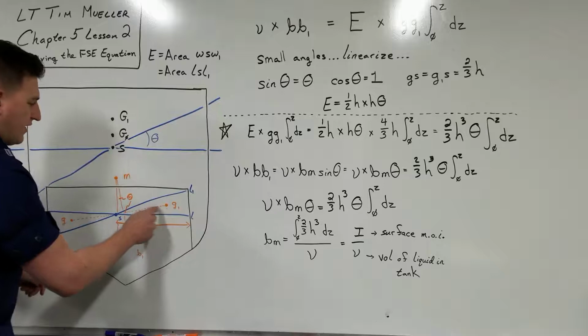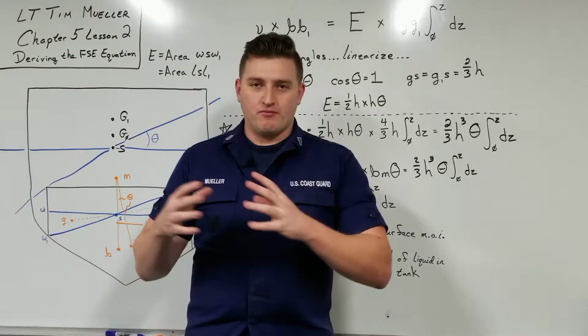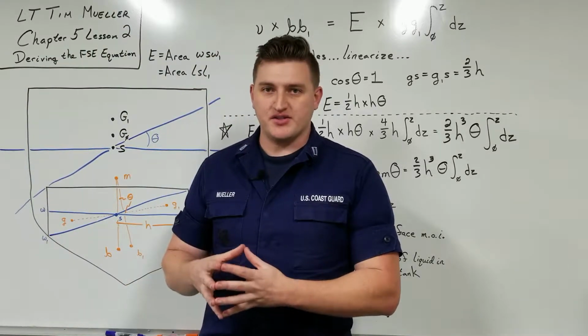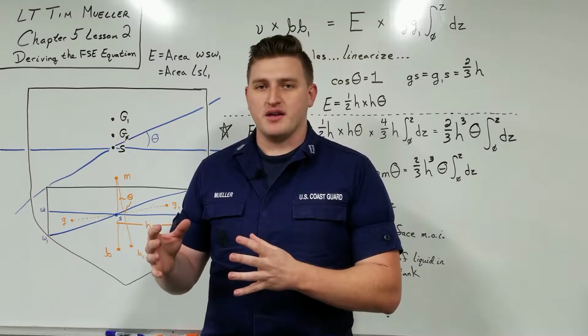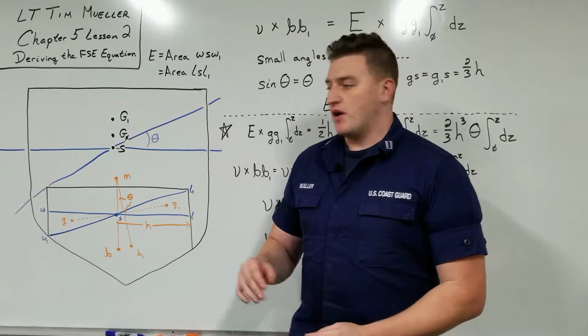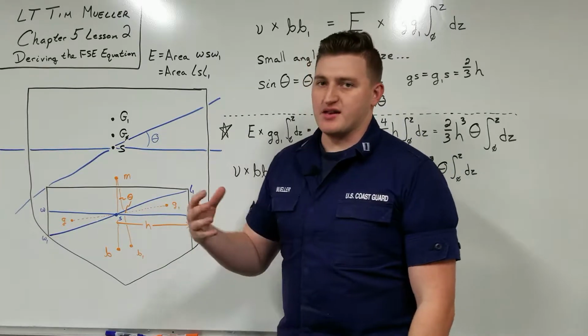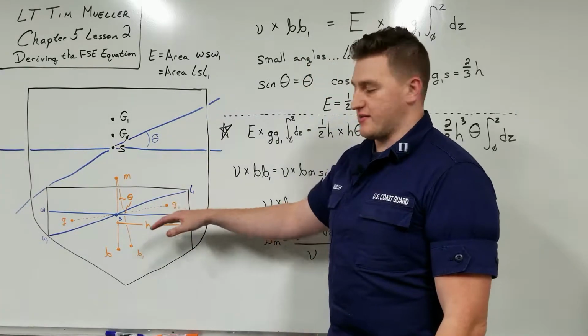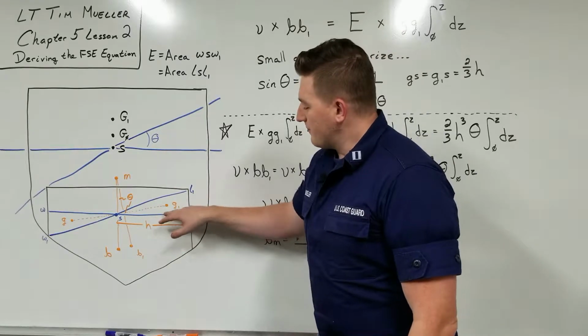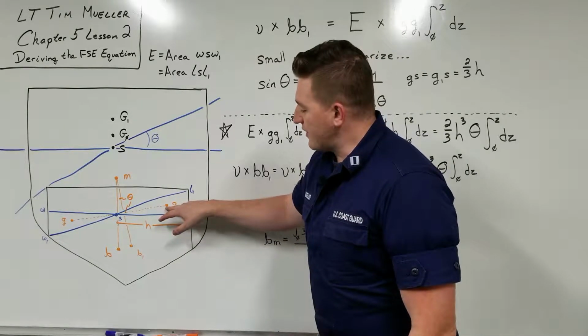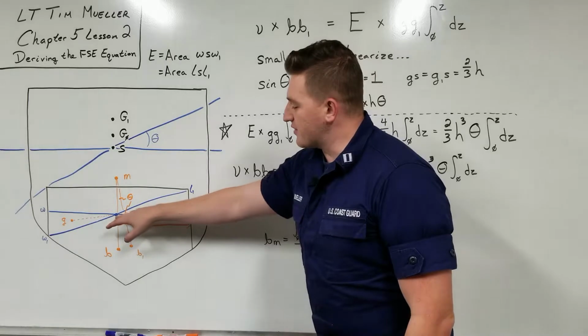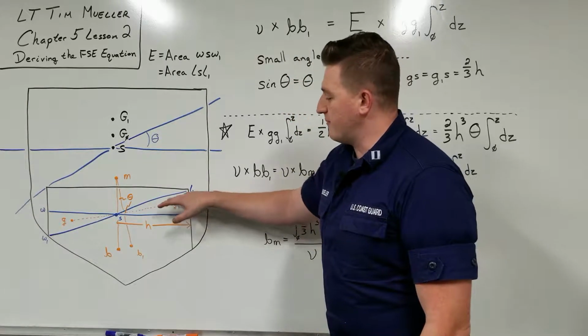This center of gravity, we talked about in lesson 2 of chapter 0: center of buoyancy, but more specifically centroids. The centroid of this wedge is also in the same spot as the center of gravity, assuming it's homogeneous. So our center of gravity is 2/3 away from the pointy end, or 1/3 from the big end.